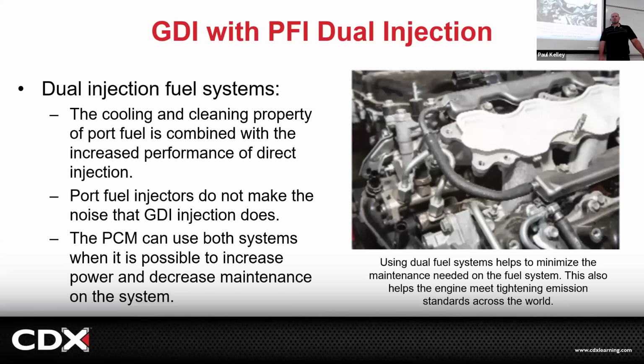What's left? If it's got good spark and good compression, what's left? Fuel. So compression and spark are good. Fuel's left over. What's wrong with the fuel? I don't know. Wait a minute, this system has a direct injector and a port fuel injector. Is it a problem with the direct or the port? I don't freaking know. So he called me and I was like, you know what? I haven't seen that really, but let me talk with some people. I talked to a couple of former students, friends, some tech people, and we all kind of agreed on how to proceed with the